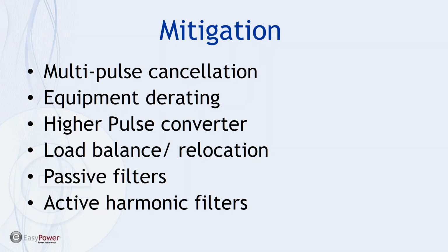So again, where we've gone with this is a discussion on how to go about preferably generating a harmonic signature when a system's commissioned or when a load flow study is done, and especially identifying potential areas that are sensitive to harmonic production, and recording those values or that model such that as things change or system capacity is anticipated to change, you can predict what the results and what prevention could be in place before you actually run into problems.